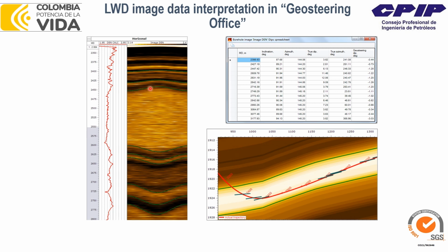formation cross tops is marked with the sinusoid, which is the green line here. Okay, and depending on the amplitude of this sinusoid and depending on how much it is centered, the formation dip will be calculated. So you can see a few of them, right? 1, 2, 3, 4, 5, 6, 7, 8. So all these are calculated here in the software, and every formation dip is marked at the curtain section.